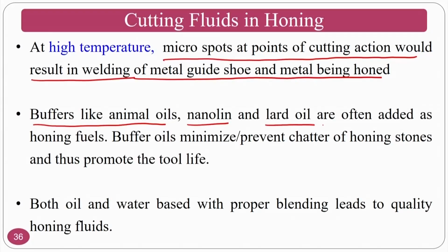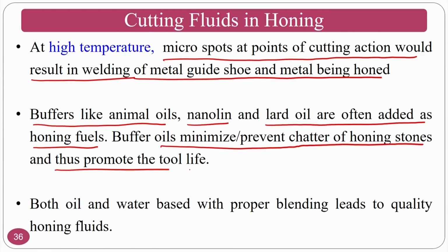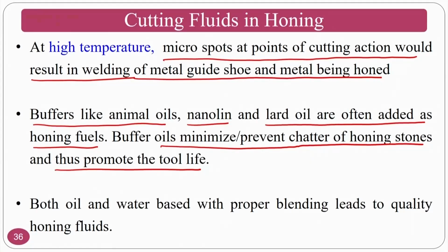Buffers like animal oils like lanolin and lard oil are often added to the honing fluids. These buffer oils minimize or prevent the chatter of the honing stones and thus promote tool life. That means that some buffer will be added to the cutting fluids so that chattering will not take place. Both oil and water based fluids with proper blend will normally be used.